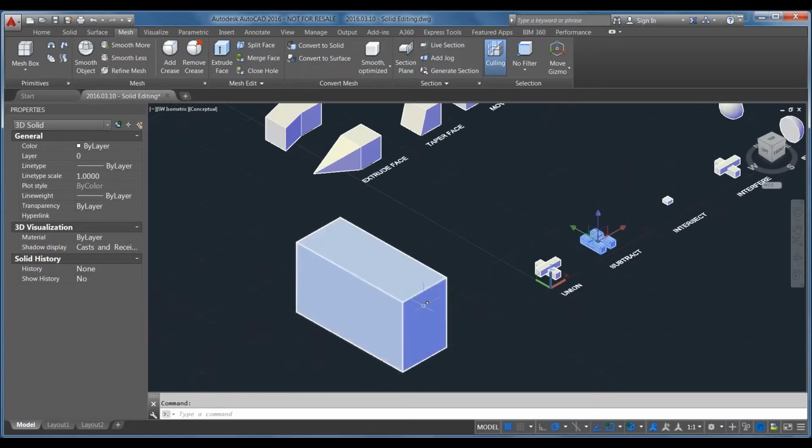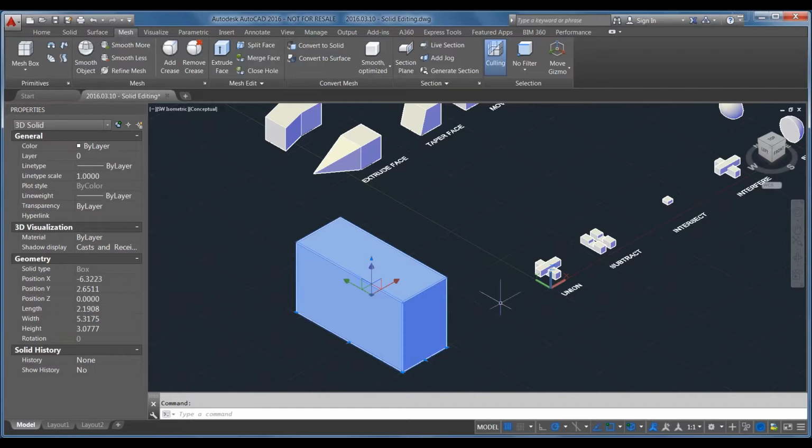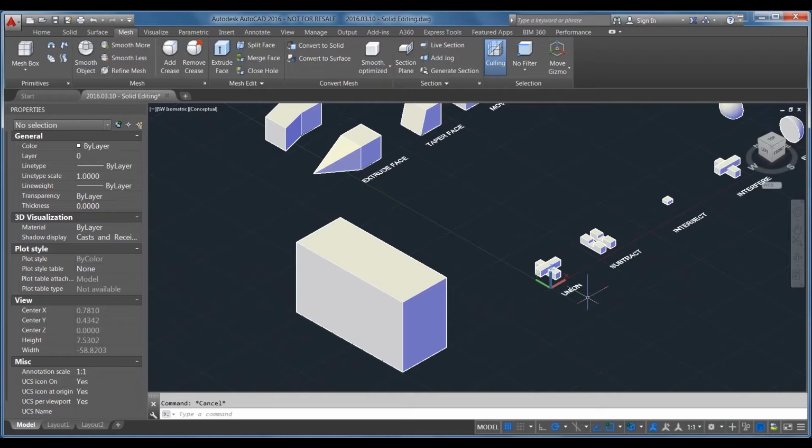Every box will have 6 faces that make it up, and they all have those properties in common, so you can change the height or the width, and AutoCAD knows exactly what to do with that. Once you start changing it into a unique shape, you lose the ability to use those grips because it's unique and doesn't share properties with every other box or every other sphere.